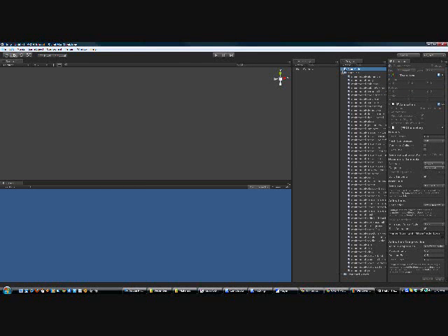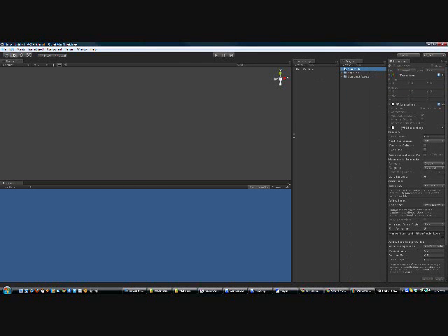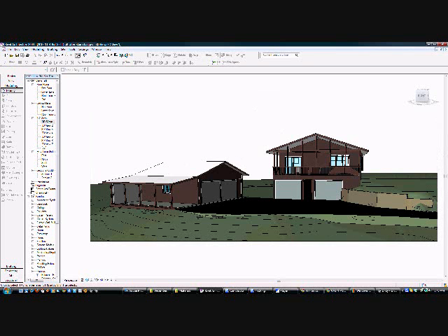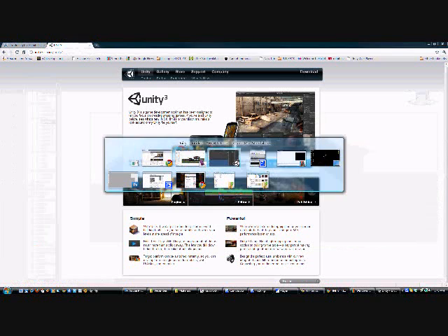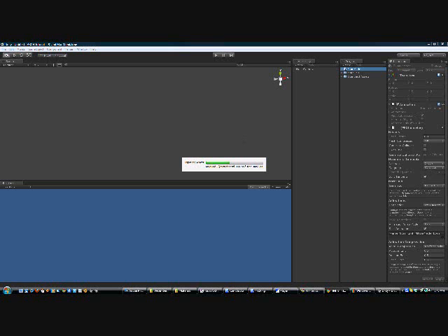So we have this model, and sometimes you have to go back to Revit and then back into Unity again. And there, it found the FBM. When you export as an FBX, it will also create an FBM file. Within the FBM file are the materials that were used within the scene. Okay, once those textures and materials are finished uploading, you can now go and you'll see in the project pane,